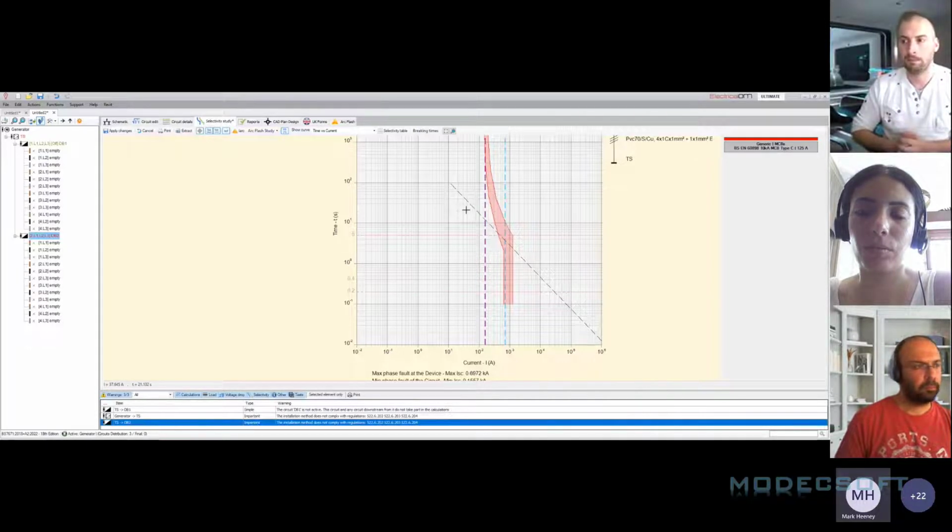Yeah, I've kind of been doing it on the long hand side, because we use a lot of DC stuff that is only supplied by batteries or rectifiers that can only deliver so much fault current, and I'm worried that I'm going to overheat my cables before the device finally trips. And this will tell you that. Perfect, thank you for that. That was worth logging in for. Great.